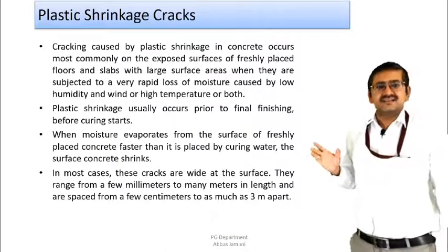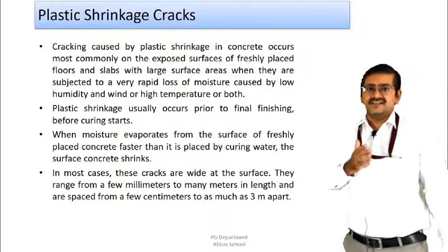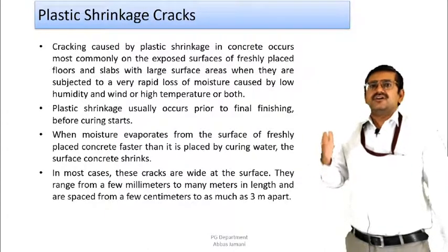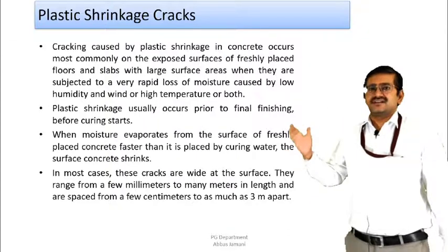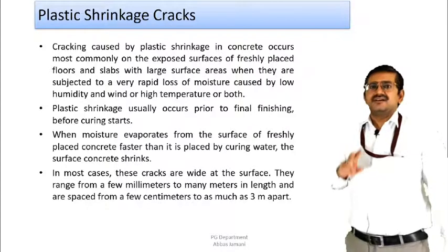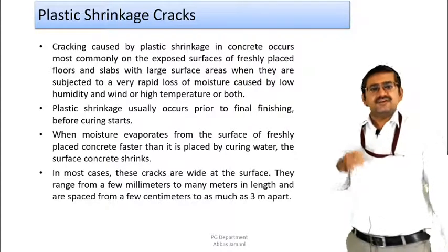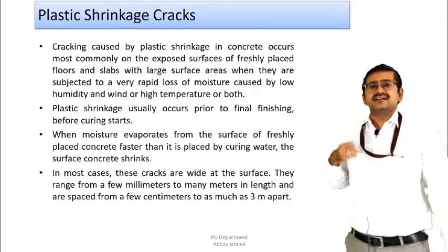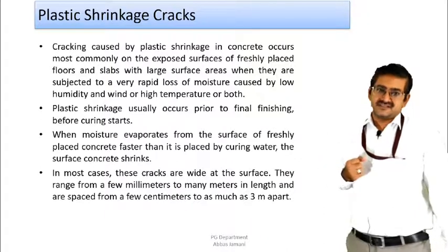Right? Plastic shrinkage cracks usually occur before the finishing stage. That is, they occur between the placing and the finishing stage. So once the concrete is placed and before the finishing and curing are done, between these two stages, the occurrence of plastic shrinkage cracks is likely. When moisture evaporates from the surface of the freshly placed concrete faster than usual, then plastic shrinkage cracks are likely to occur.